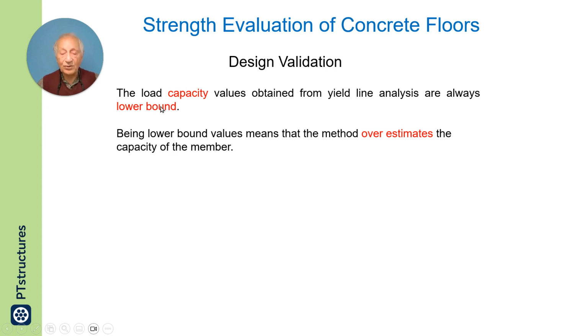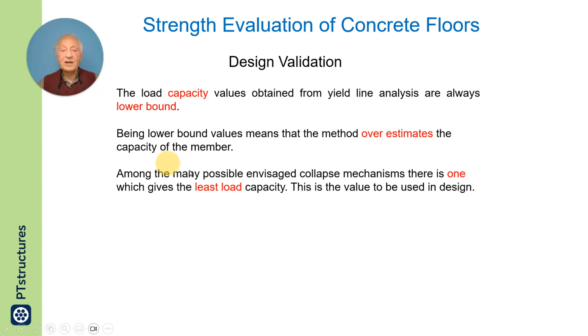But you have to make sure that the capacity you calculate is more than required, because the method, being a bound, can overestimate the capacity of the member.